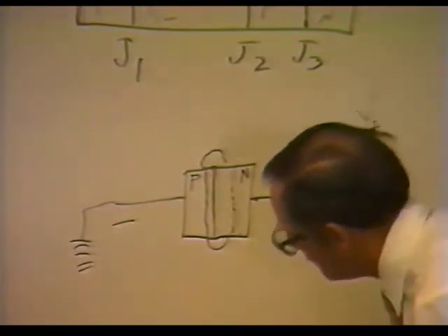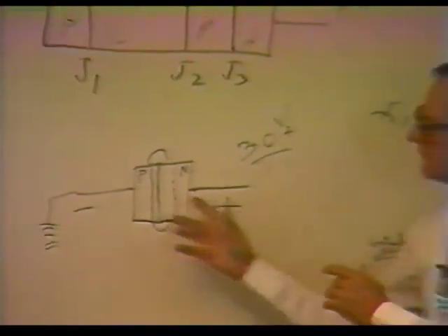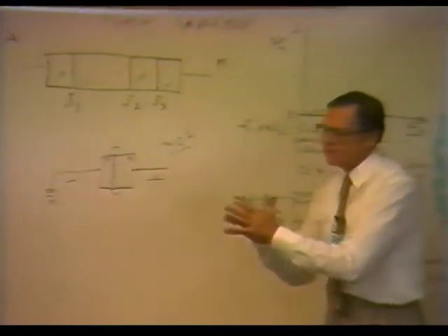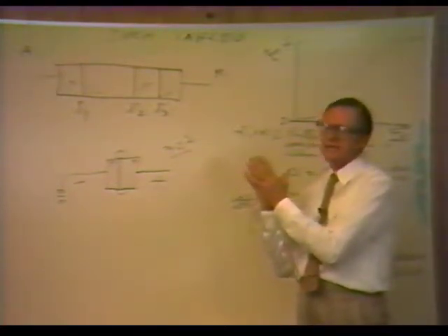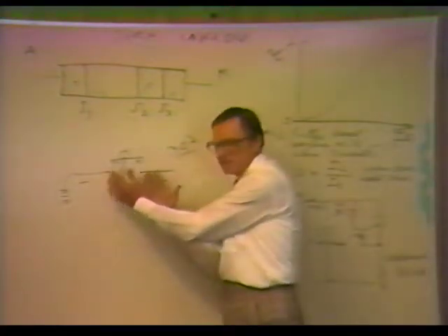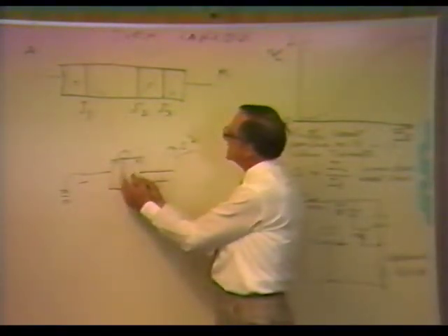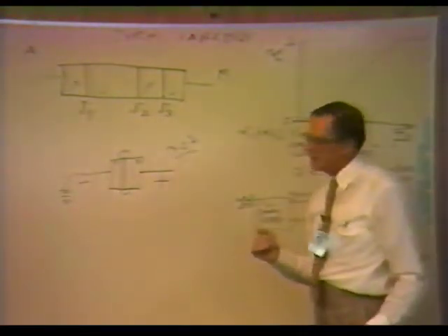Now, what has moved? And this is important. The atoms have not moved. The silicon atoms and the silicon lattice work are intact. Every atom is intact. The carriers or the electrons are still spinning around. The impurity atoms are still intact. Nothing has moved but the loose valence electrons and holes, the carriers, have moved back from here. The atoms themselves are still in place, the silicon atoms, the impurity atoms. So that has not changed. All we have done is pull back the carriers.